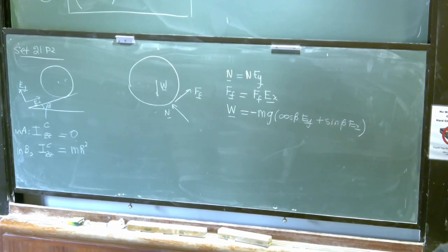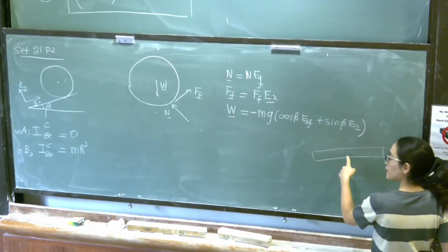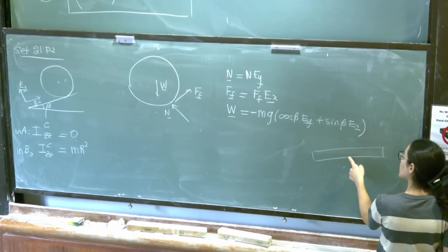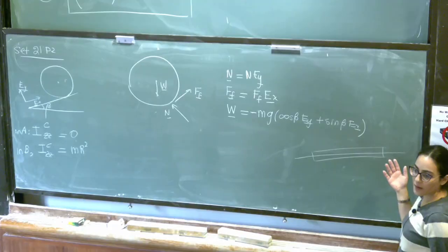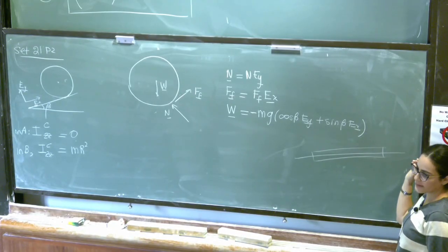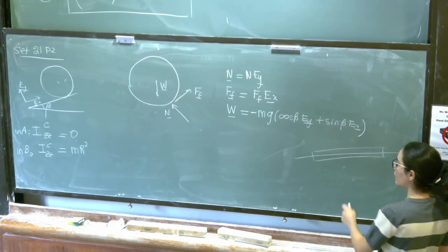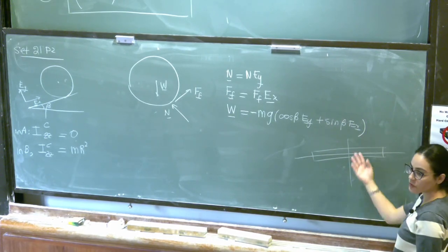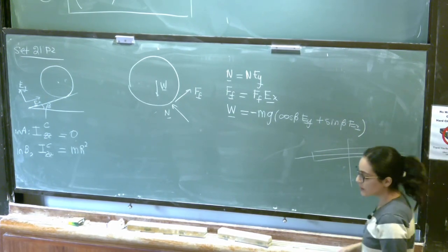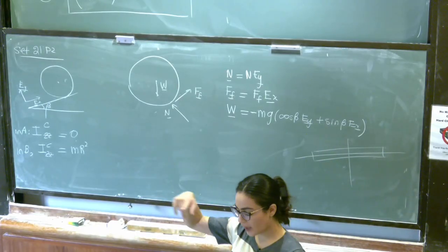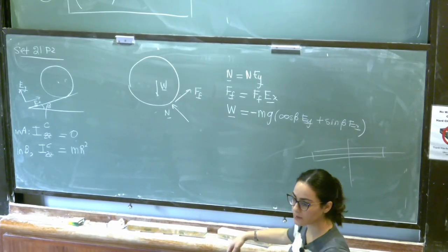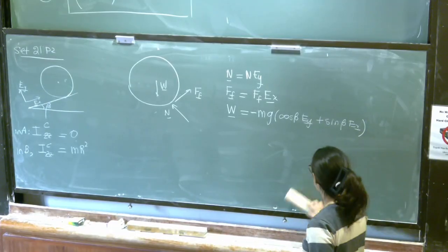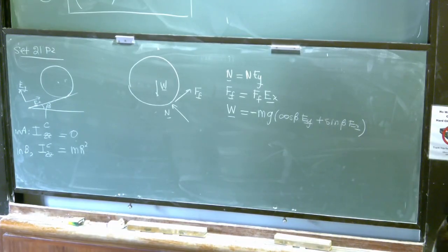So this is the bar, right? This is the system in A. And I want to look at the mass distribution of this bar about this axis. But all the mass of the bar is very close to that axis, right? If I were to look at the moment of inertia about here, then here I have a non-zero mass distribution about this axis. But about this axis, it's 0. So that's what's happening. In A, I'm rotating about this axis, and all the mass is concentrated about this axis. So if you were to apply the formula, the integral of x squared plus y squared dm, x squared plus y squared is 0. Great. Any other questions?